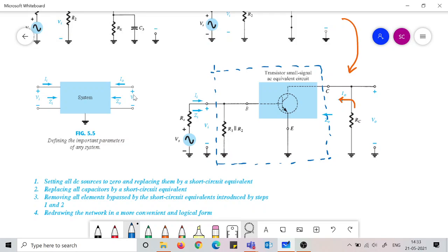And if the output voltage becomes known, we can always calculate the I0 if the Z0 is known. Similarly, Vi is given on the input side, and Zi is given from the two-port system parameters, so Ii can be known. So the different variables Vi, Ii, I0, V0 get very easily known if we know the Zi, Z0 along with the voltage gain of this network.